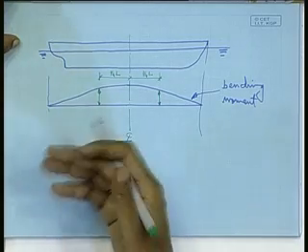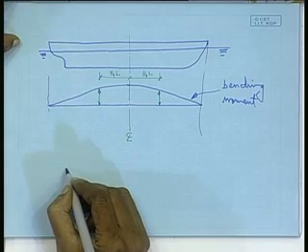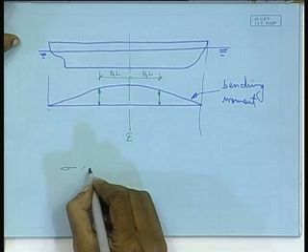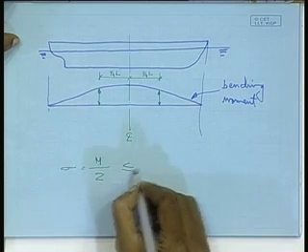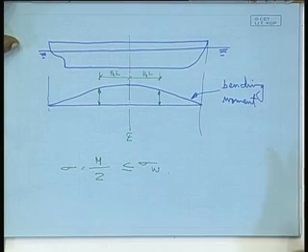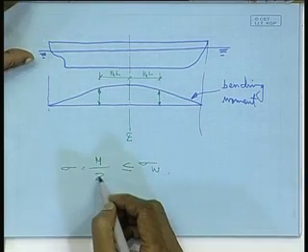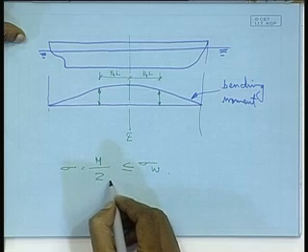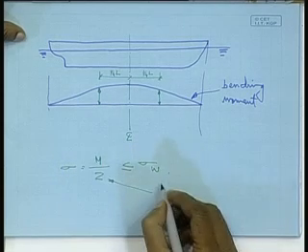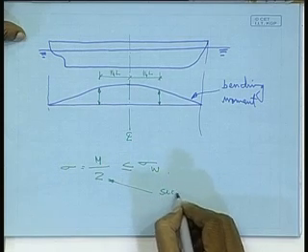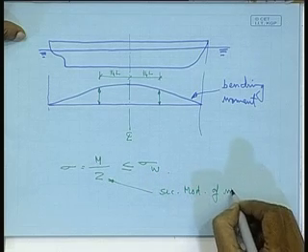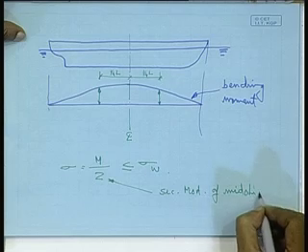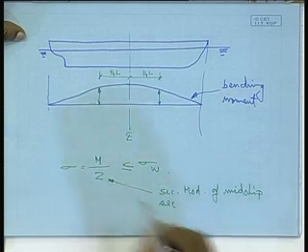Why? Because the section modulus which we will get from the midship section should be such that the stresses we get, right, should be less than or equal to the working stress. This is the primary thing, right. So this Z is the section modulus. This Z is the section modulus of which one? Of the midship section, right. Section modulus of the midship section. Why is it important? Because there I have the maximum moment,